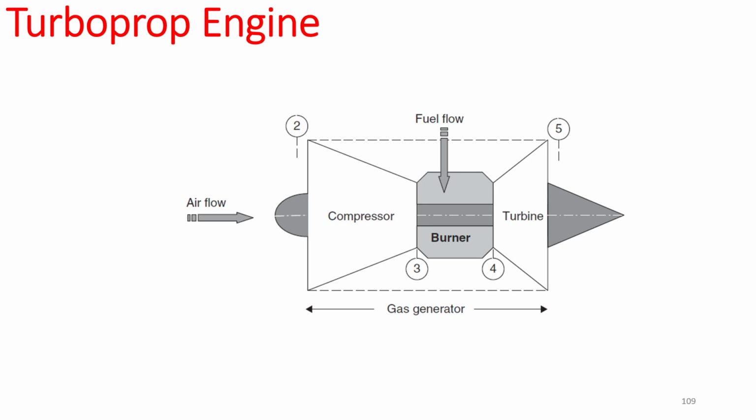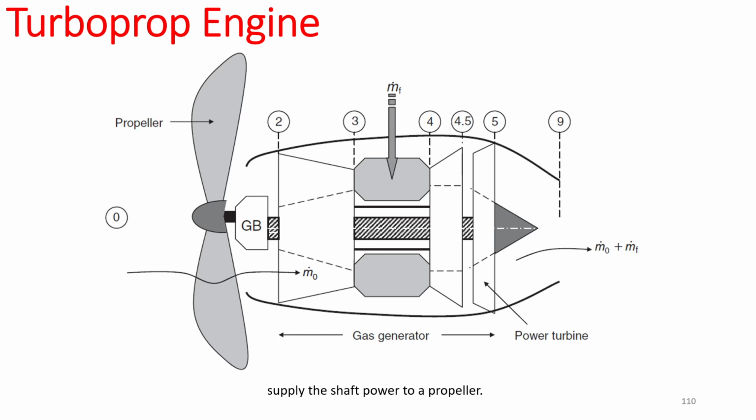And we have already seen different methods you can use that leftover energy to produce more thrust or to increase the efficiency. The turboprop analysis takes that leftover energy out of the turbine and gives it to the propeller, essentially before station 2, before the compressor, right? So, but how do we do that? Well, how do we transfer the energy from the station point?